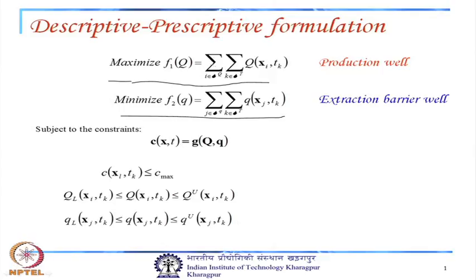Summing over all spatial locations and all time periods, we maximize the production well pumping and minimize the pumping from the extraction barrier wells, for location j and time period k.